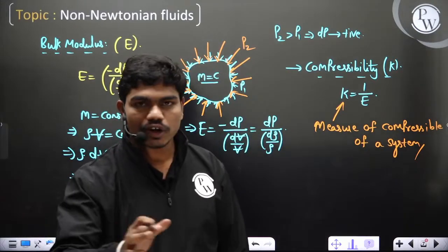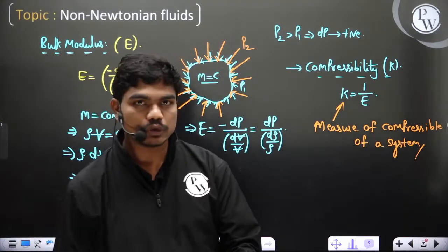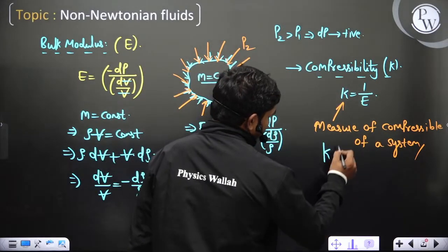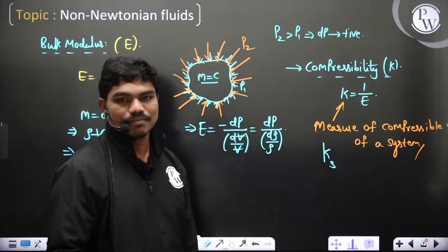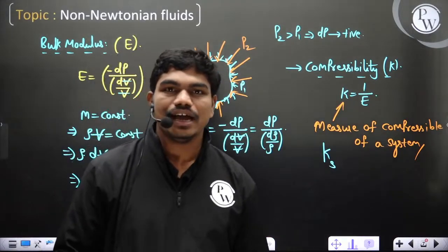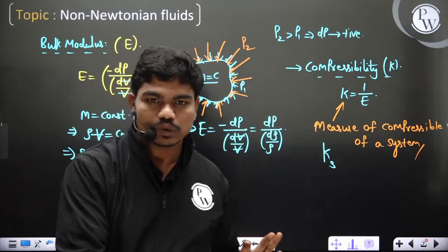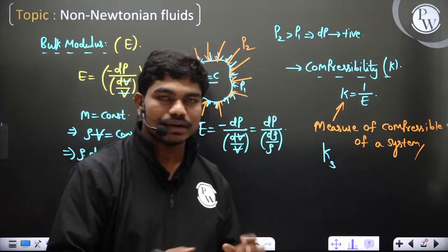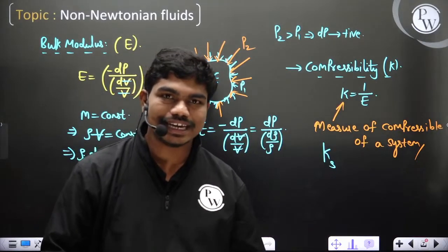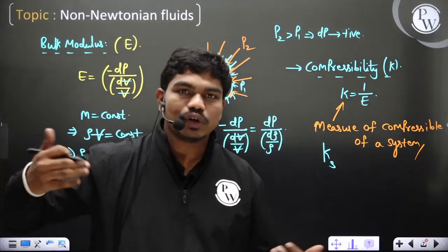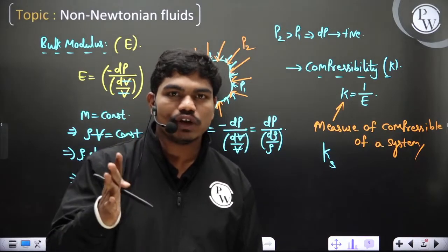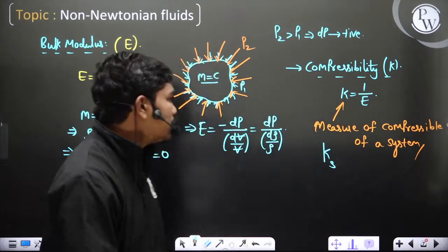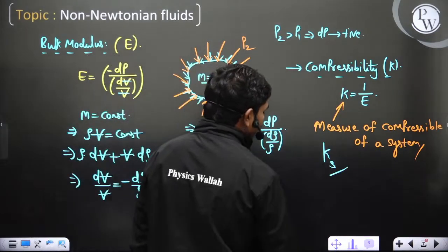Right now we are not doing that, because I think Shivam sir might have already taken you through it in properties of substances. Now you can see this bulk compressibility is what we generally take as adiabatic compressibility, because adiabatic is generally easy. And in our fluid mechanics, in this particular course, we don't interact with any heat interactions in the fluid. Like for example, later in flow through pipes or at any location, we don't deal with heat interactions. Normally we'll have only 4 equations and 4 unknowns. We will see what they are, but this is the adiabatic compressibility.